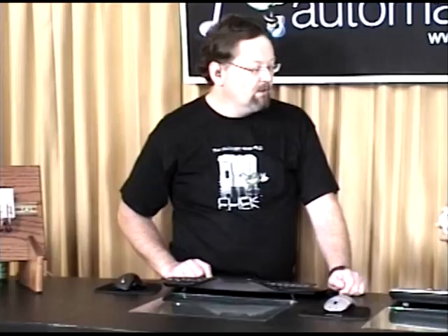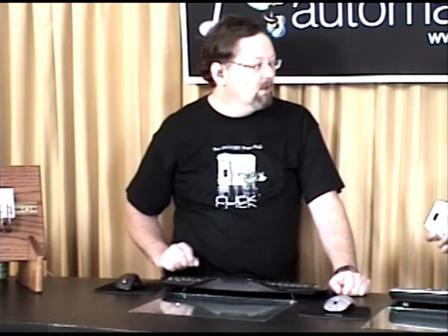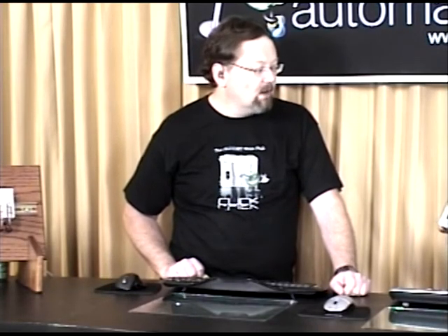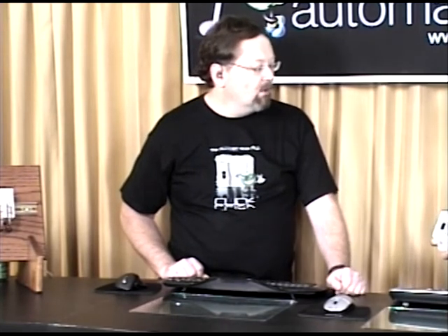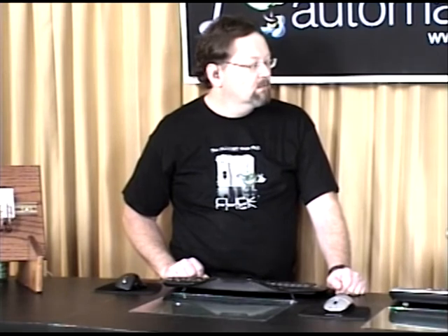Oh yeah, sure. Like I said, all you do is go back into the setup and the system configuration, change the processor type to match whatever the new processor you're using is, and the program will convert right over. Okay. So no problems there. No problem. And you could switch back and forth. Obviously, if you have analog programmed, it's not going to work in one of these. Certain features may not be available. If you take a standard program and put it in a basic, and you're using a real-time clock, obviously it's not going to work, because the basic doesn't have a real-time clock. Right.